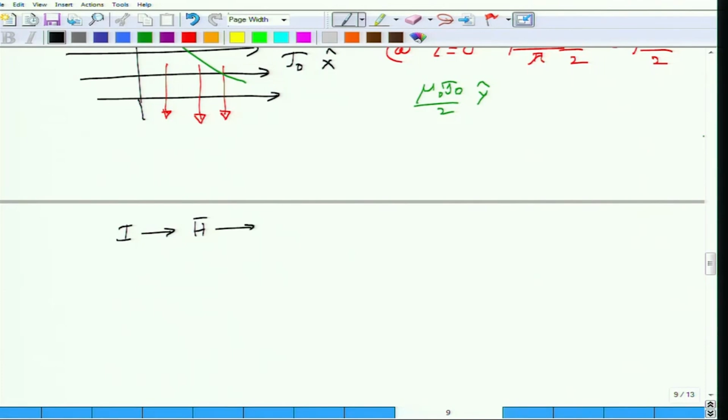And the reason to introduce this H field is this: we imagine that current actually generates the H field, and this H field is related to the B field via the material properties, as opposed to electronic properties or properties of the electrical materials. Magnetic materials are much more exotic. They are highly nonlinear most of the times, and they also have some sort of a memory in between them. This is called hysteresis. You must have heard about hysteresis.